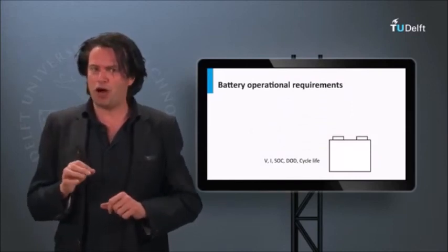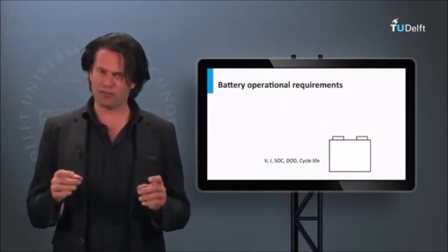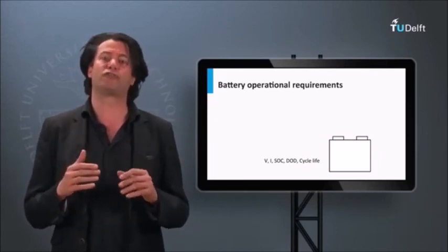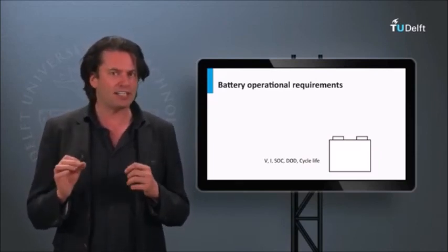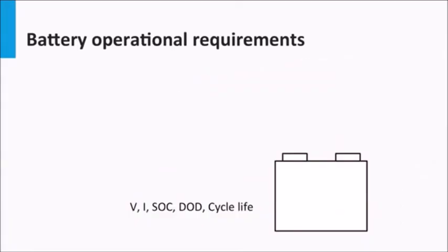In the previous video about the battery parameters, you have learned the importance of having the right amount of current and voltage being provided to the battery. You know that the battery is an electrochemical device which requires a small overpotential when it needs to charge. However, battery technologies have strict voltage limits required for their optimal functioning. Also, the amount of current sent to the battery by the PV array and the current being discharged away by the load have to be within required limits for proper functioning of the battery.